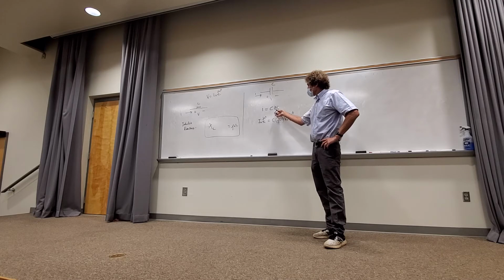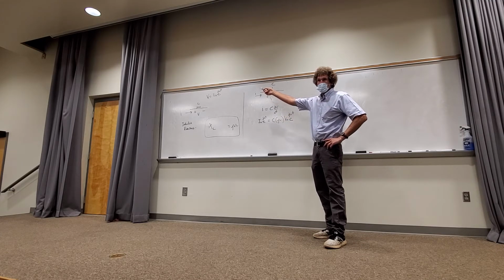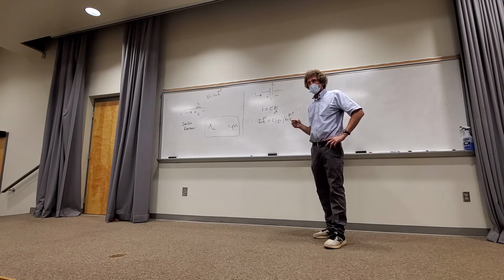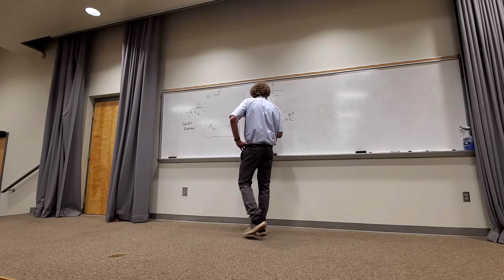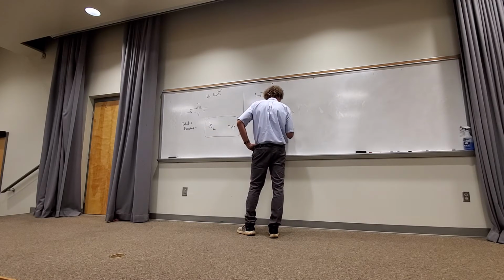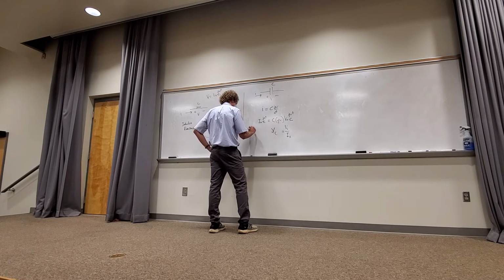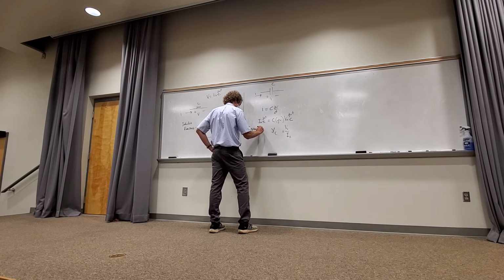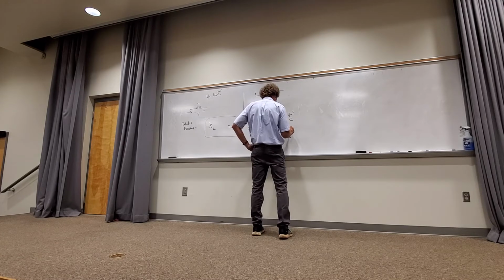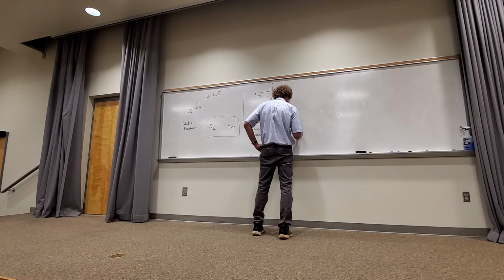Right here, you're taking the derivative with respect to time of the voltage, right? The voltage is going to be V naught e to the j omega t. Do you see it right there? Take a derivative, you're just pulling out the j omega, right? Now if you look at the ratio of V to I here, this will be called the capacitive reactance. And what it'll be is 1 over j omega C.